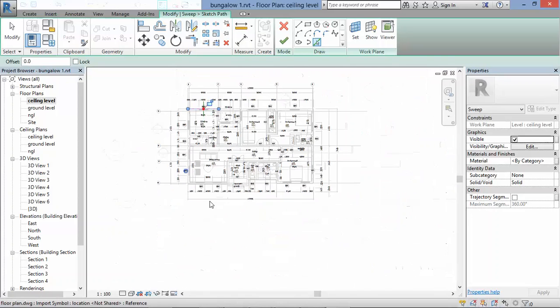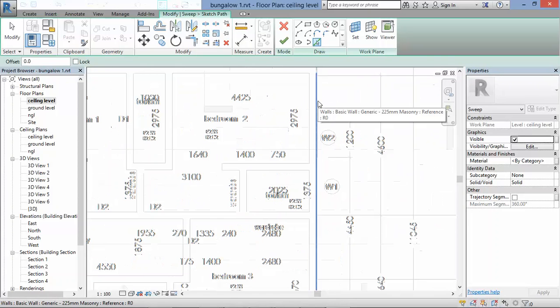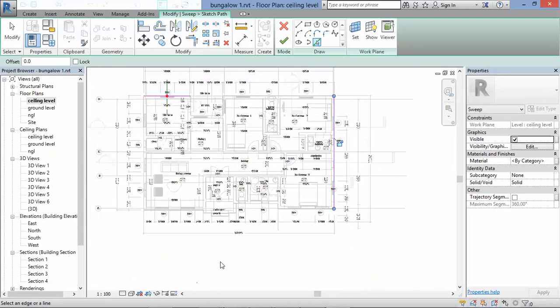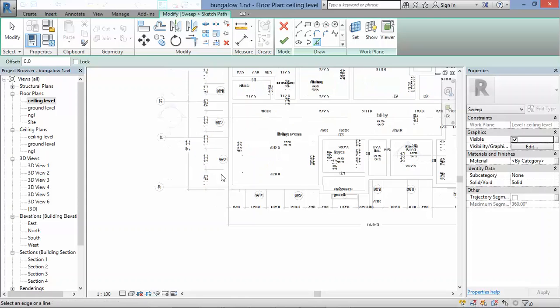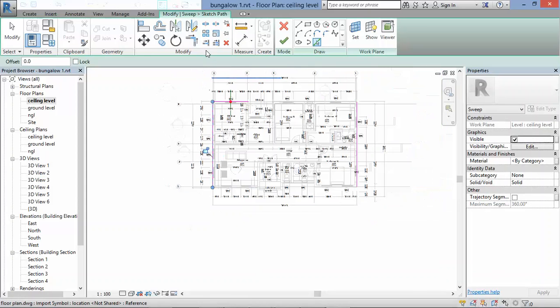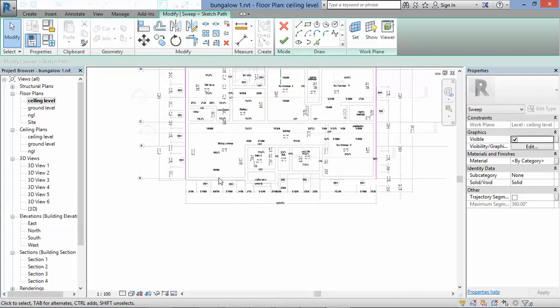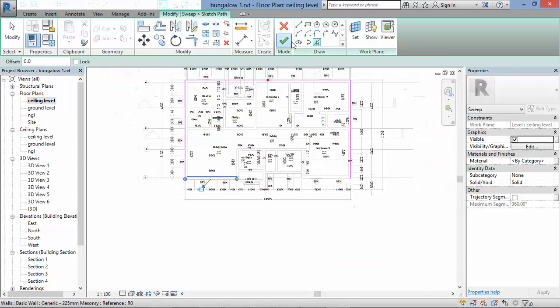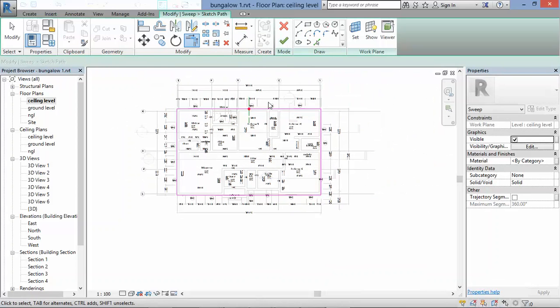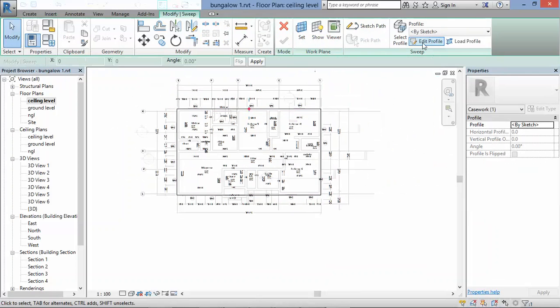You know, the concrete fascia does not have a lot of overhang from the wall, maybe like 100 mm or thereabout. So after I've gotten the outline of your walls, you can now trim. I mean this one. You can now trim like that. Then when you have trimmed, you now check. Then you now come to edit profile.